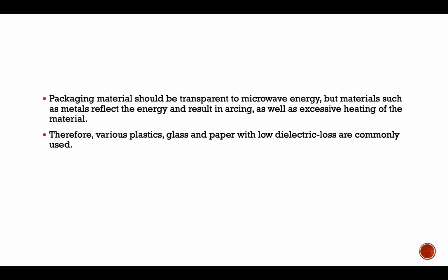Packaging material should be transparent to microwave energy, but materials such as metal reflect the energy and result in arcing or sparks, as well as excessive heating of the material. Therefore, various plastics, glass and paper with low dielectric losses are commonly used.